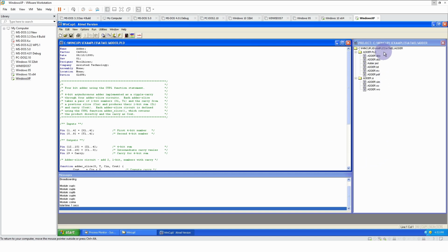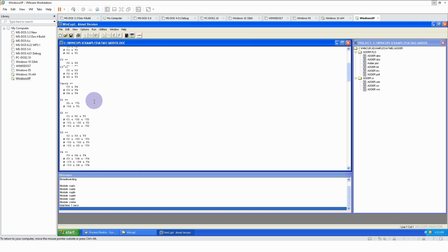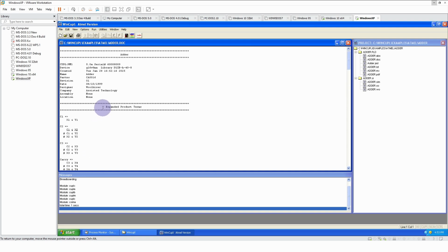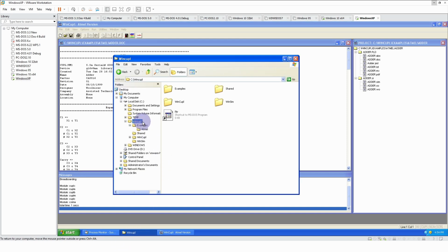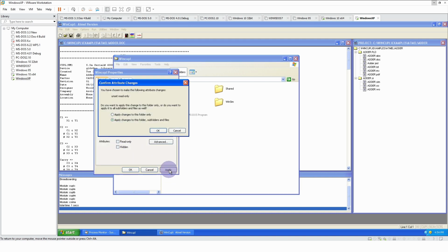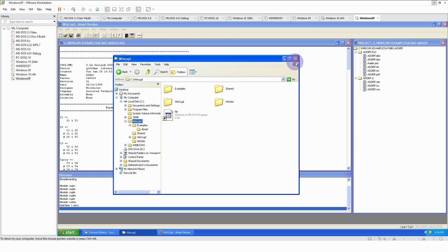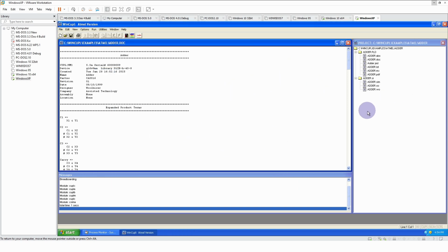And we can also see that this project view does actually make things a bit easier. So for example, if we wanted to have a look at the output files here, we could do so. So it certainly made sense the way it was working. I've not been able to get to the bottom of what was causing this problem. You do need to change the permissions on WinCUPL running under Windows XP to give update access. So you do that and apply it. Otherwise it doesn't actually save the changes you make to the configuration. But other than that, there were no other changes I needed to make.